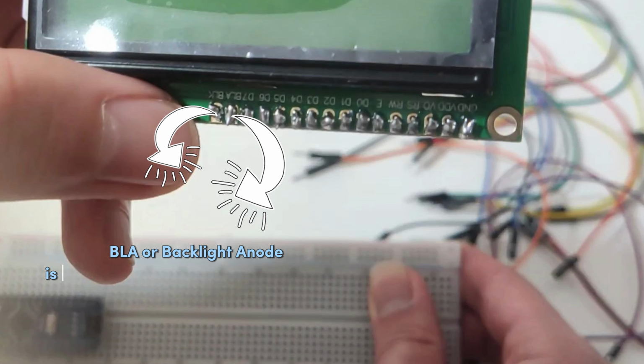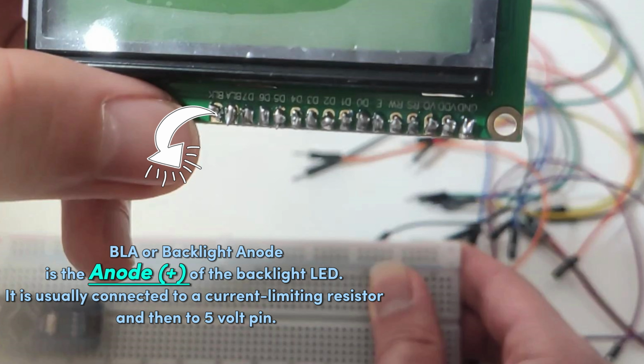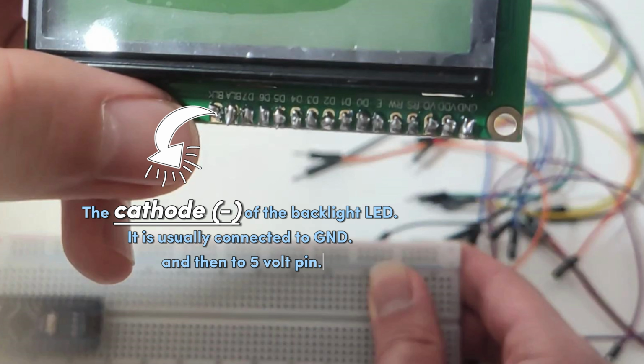As the last 2 pins, we have BLA and BLK. The BLA, or backlight anode, is the anode, the plus of the backlight LED. It is usually connected to a current limiting resistor and then to the 5-volt pin. The BLK, or backlight cathode, is the cathode, the negative of the backlight LED. It is usually connected to GND.